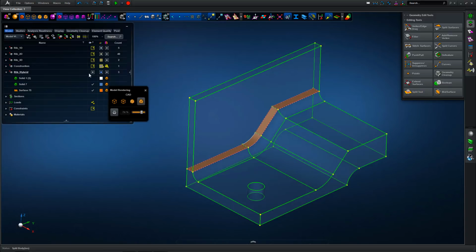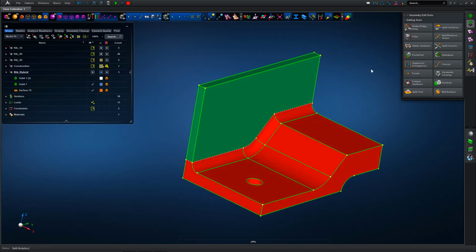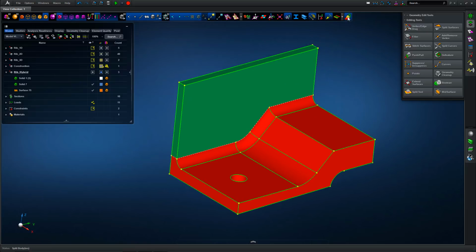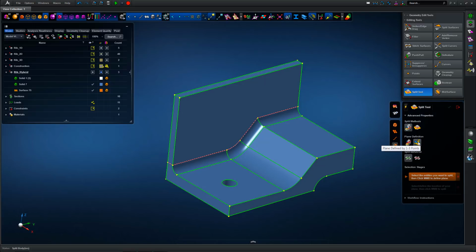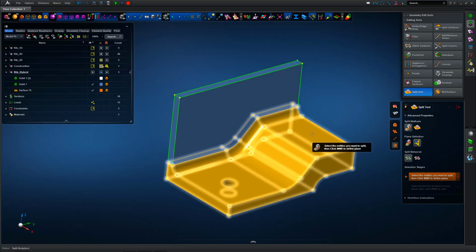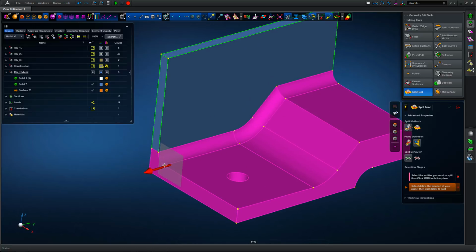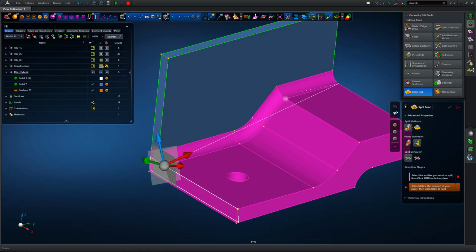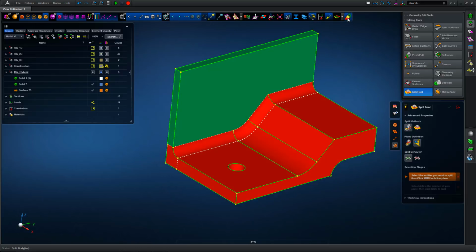And then if we show the mappable geometry, you can see that new partition that's been split off is green, which means it can be hex meshed. So we repeat this process for the remaining geometry based on, in this case, splitting planes rather than surfaces. So, studied this geometry a little bit, but know that we can basically split about a number of flat faces or flat planes, to break it down into the geometric representation.